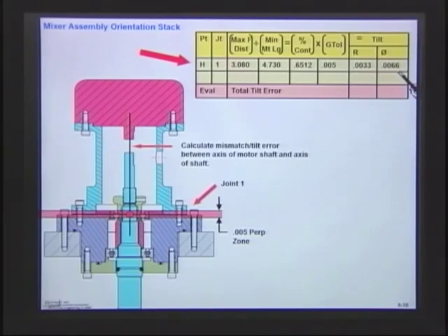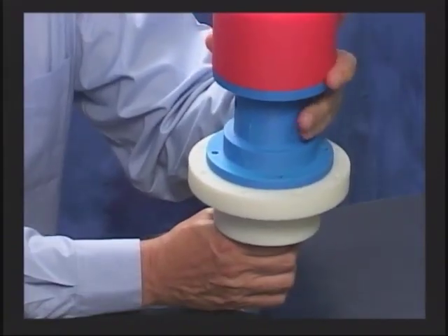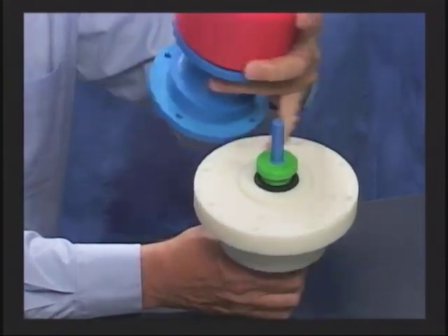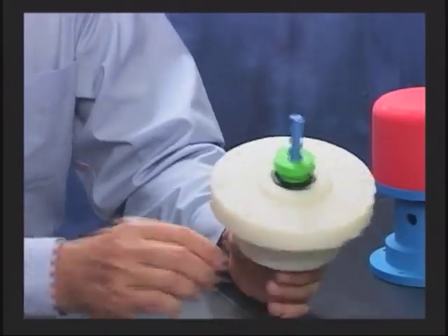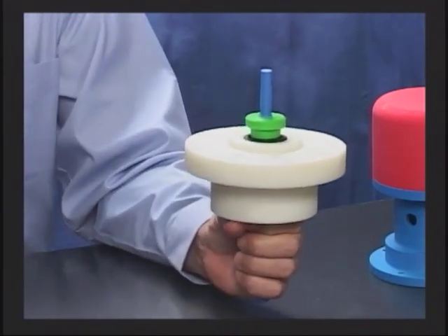Now let's take a look at our model here and notice why the amount here is double. You see, here's our part, and you see this was the face. We were on the axis. Remember, that was our datum. And you can see how important it is when you're selecting datums on the part. When you go back and you're going to do a tolerance stack afterwards, boy, everything just falls right into place when it's done nice and correct. Makes you feel good afterwards. You notice how we nicely selected the axis of the datum, and then we had the faces, and we're going right through. So initially we did those calculations right, so now it makes our calculations here, our stacks, a lot easier.